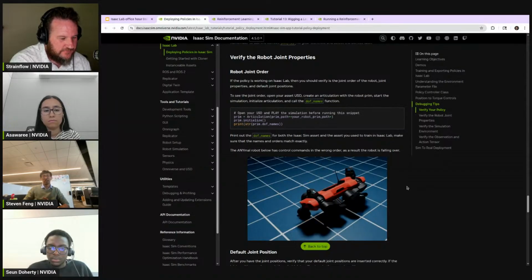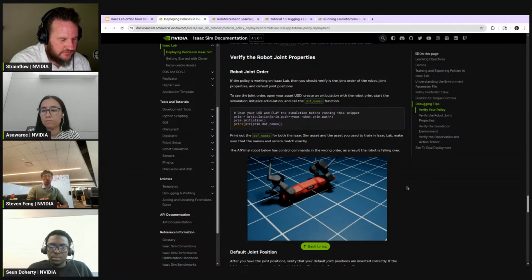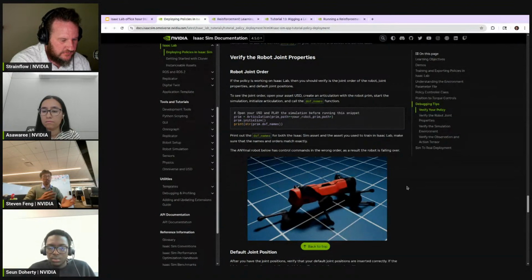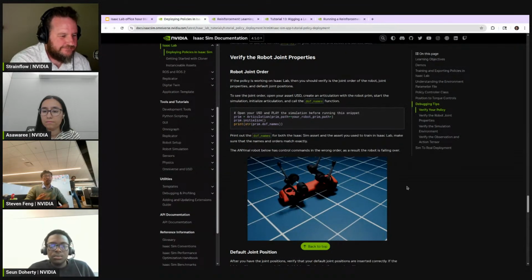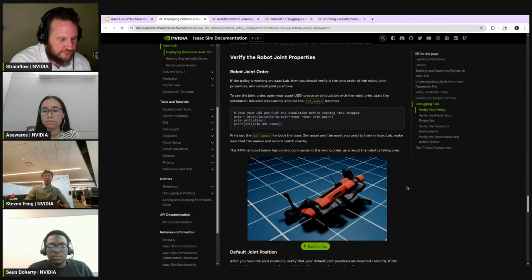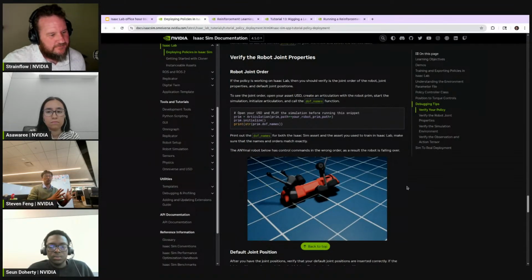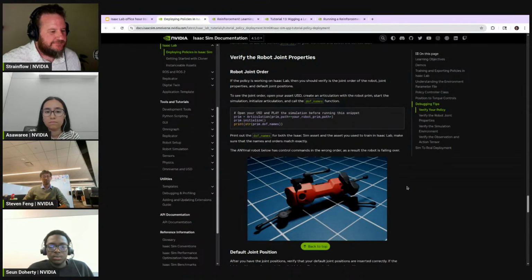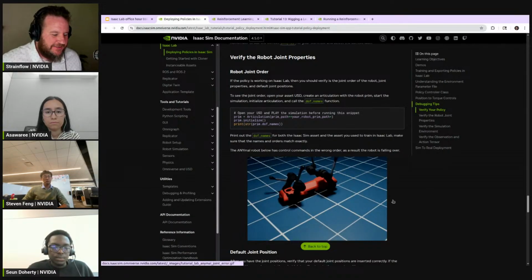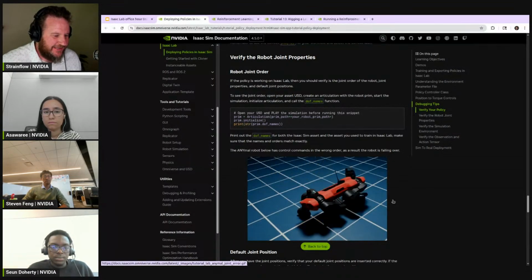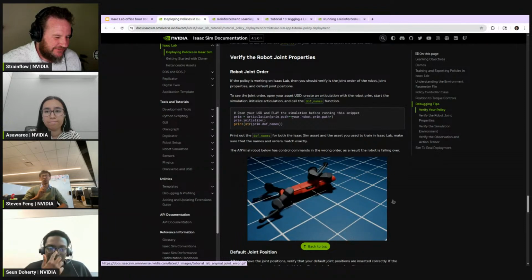Or in another scenario, let's say your Isaac Lab robot has 12 revolute joints, just like this one, but you also give it a few additional fixed joints to mount additional sensors. Then the additional fixed joints will also change your robot's articulation tree and your joint orders as well. So you may have to double check and make sure you are passing in the joint order in the way that the Isaac Sim robot expects it. Got it. But essentially, if you have a flailing robot, there's a pretty good chance that your joint order is wrong. For sure. So this should be the first thing you check.